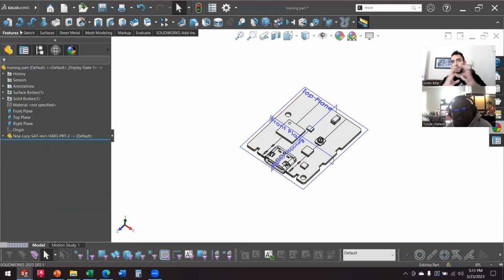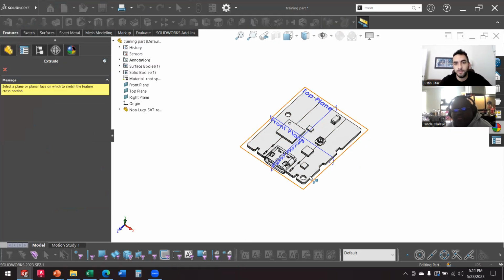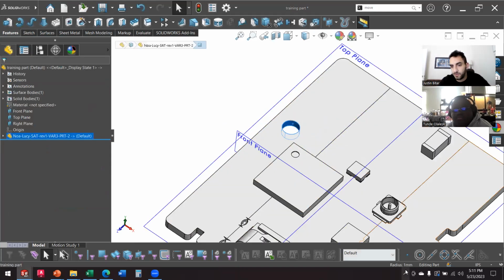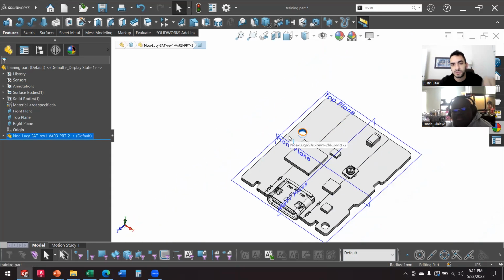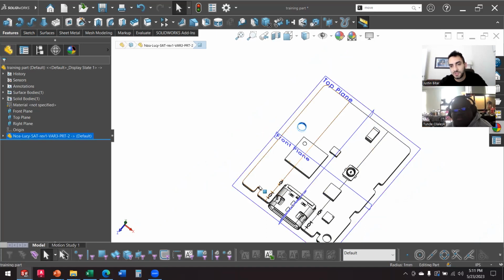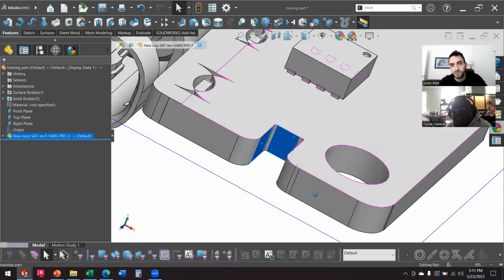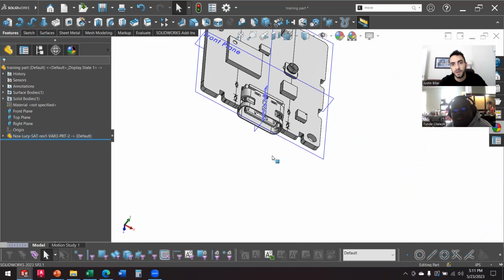I'm going to show you a couple of things here. We've got a couple of holes that we could put screws through. They're radius 1 millimeter, which means the diameter is 2 millimeters, so these would be an M2 screw that we could put through these holes. We've got some other features here that we could probably use to locate the board.